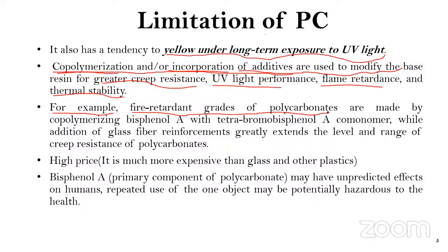In that way, these fire retardant grades of polycarbonates are made by the copolymerization of bisphenol A with a tetrabromobisphenol A comonomer.